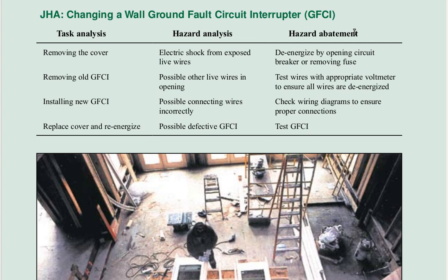Now, GFCIs must, by standard, be installed within 6 feet of any kitchen sink, face basin, any water container, wash tub, or a wet area. If any plug is to be installed within 6 feet of those areas, it must be a GFCI.